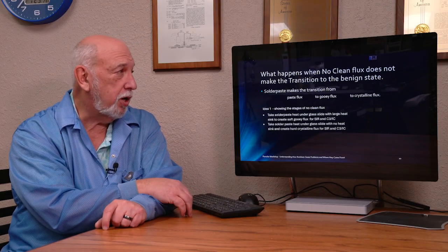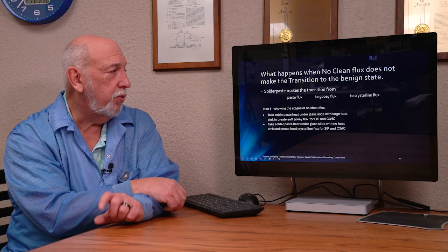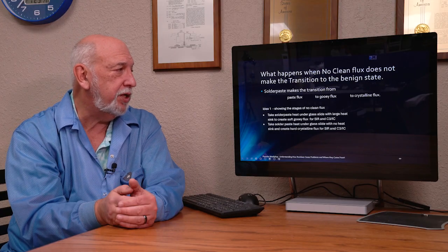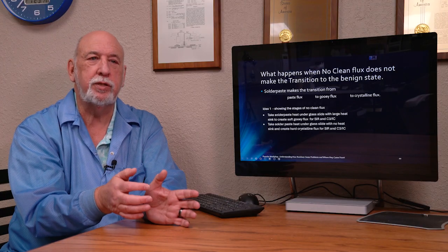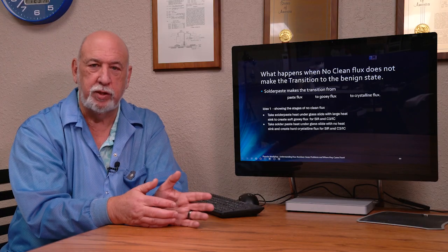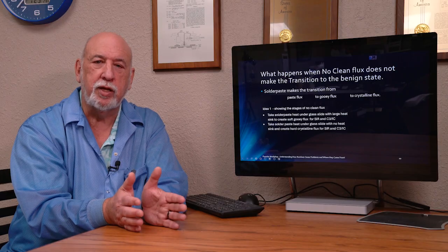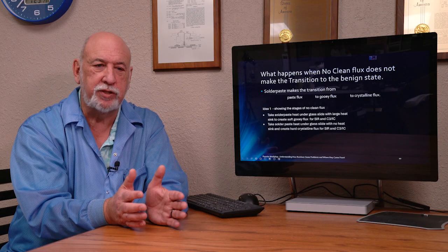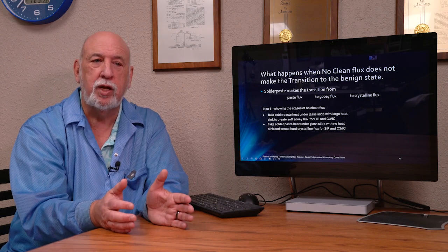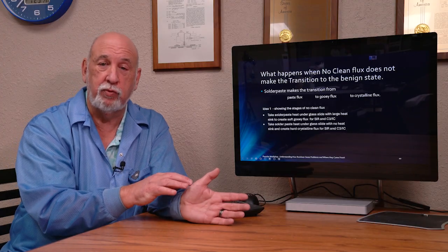And we've talked about fluxes, but one of the other things that we'll see is solder paste. We go through two reflow processes in many cases, and we're seeing the effects of the secondary soldering operation being cooler on one side to protect the first side reflow.